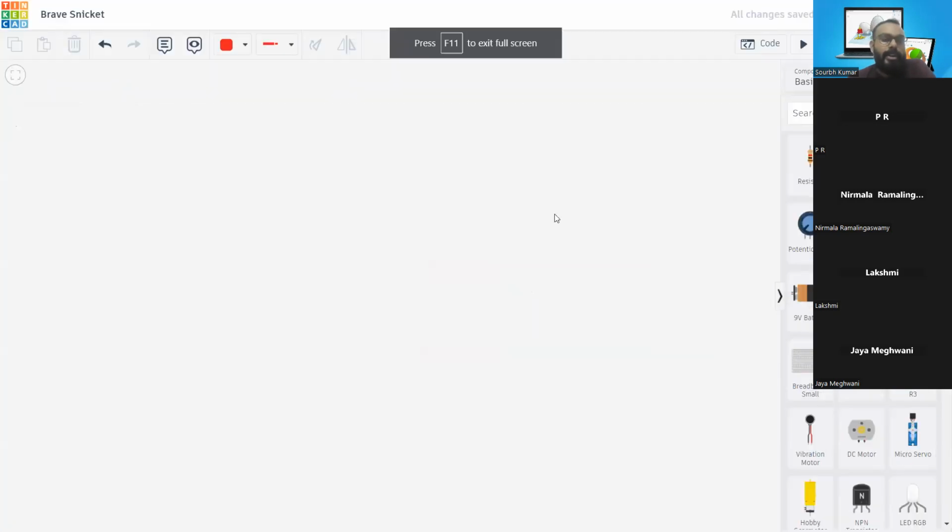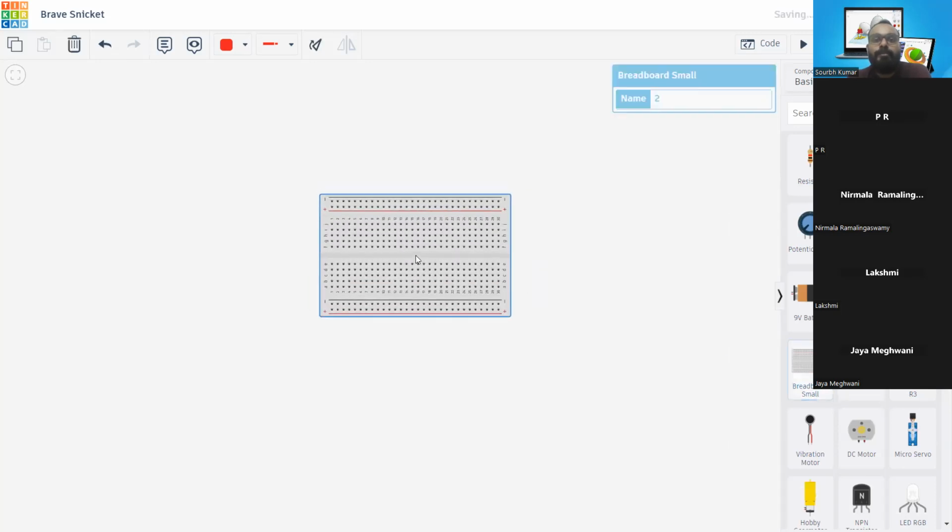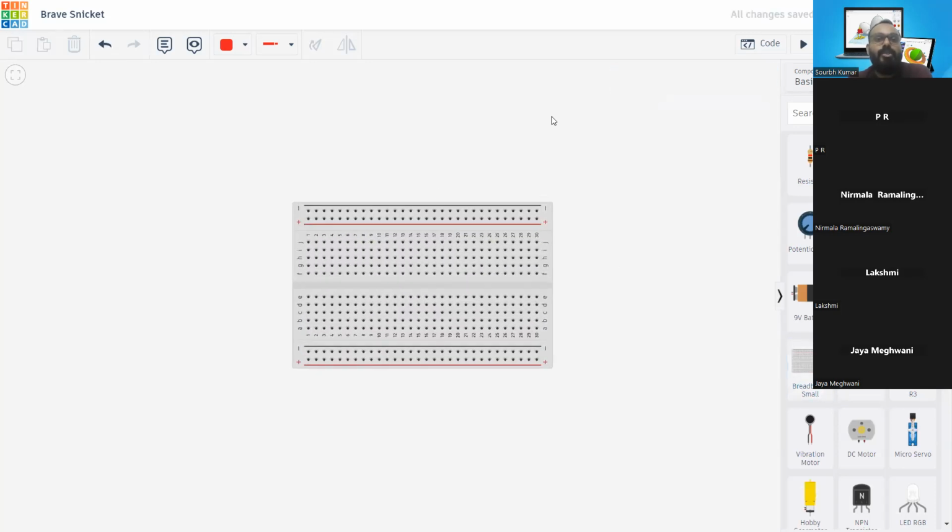Yeah, for our understanding, we can go without the breadboard, but from the student perspective, you should follow the procedure of utilizing the breadboard in your classroom. Otherwise, if you are using the LED, its pins or terminals are so delicate that you cannot reutilize them again for any of the projects. So you must utilize a breadboard for each and every project. For the smaller ones, from LED glowing to the Arduino stuff, you should utilize the breadboard in between. Otherwise, you will damage your component, and it is not advisable to do this circuitry without using the breadboard in practical application.